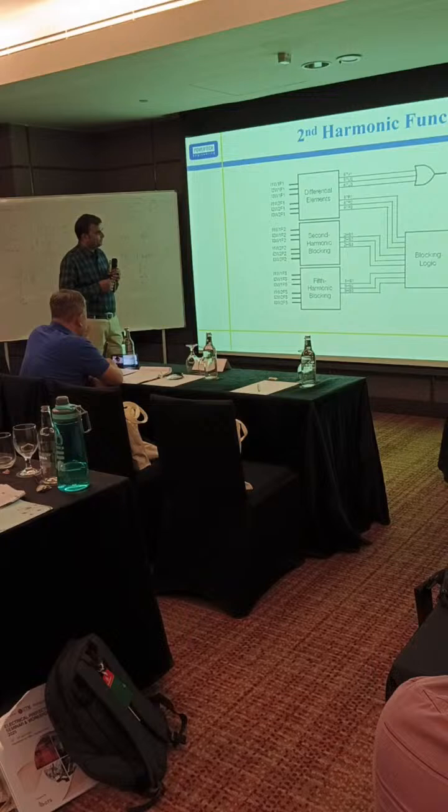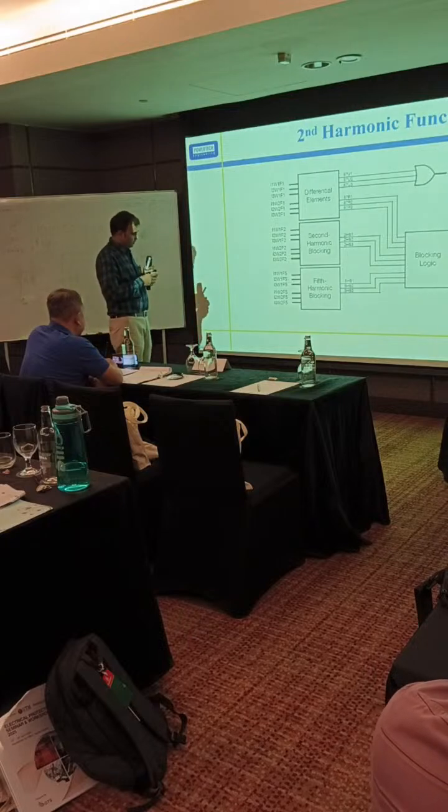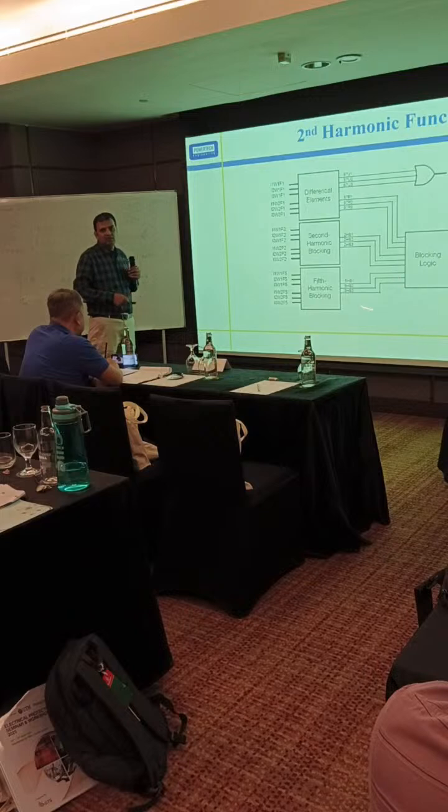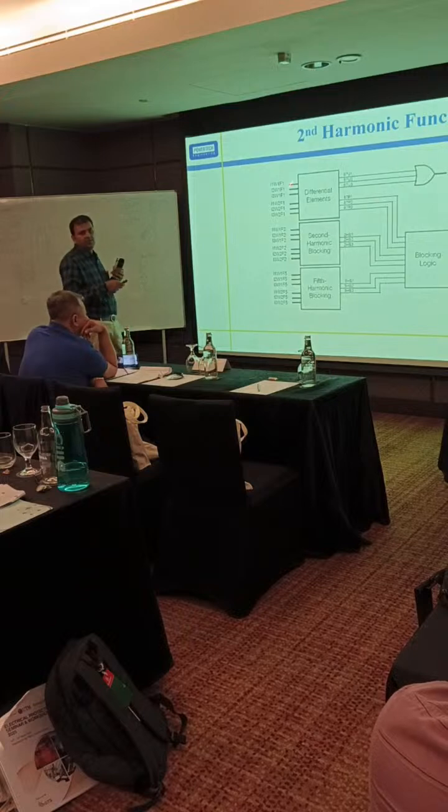Okay. So that is why this unrestrained component is independent of the harmonic. Whatever the harmonic value and all these things, it is independent of this. It immediately gives the trip command if the differential current is higher than the setting.